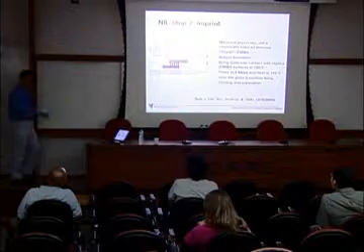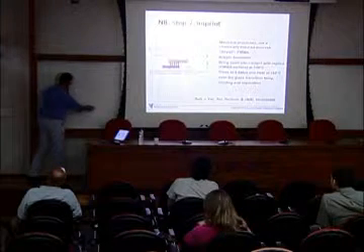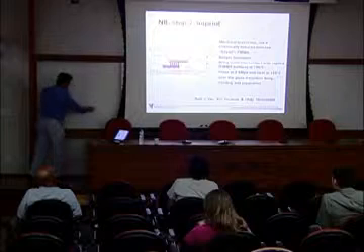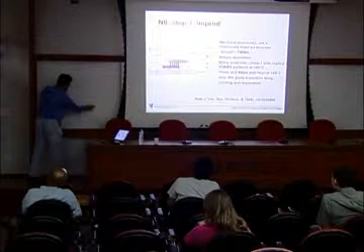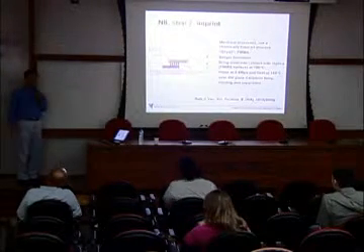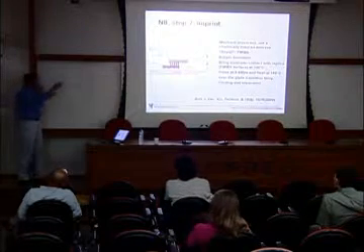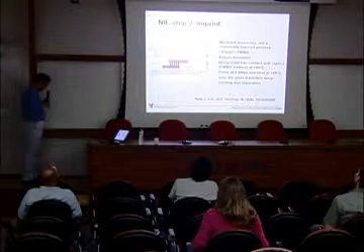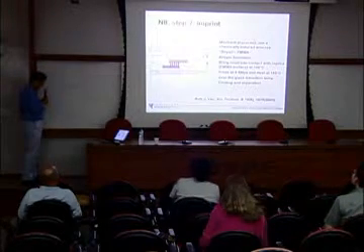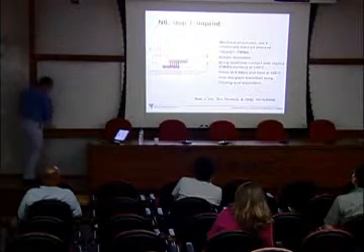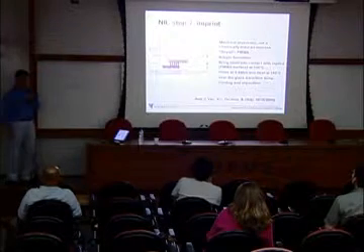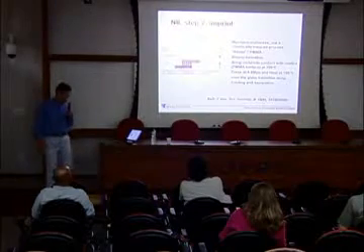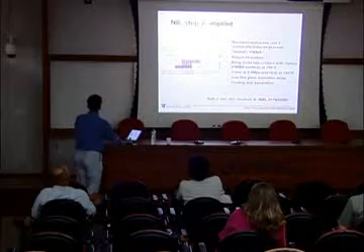In comparison with that, this structure is very narrow, so the polymer material underneath will be transported very well. So this kind of nanoimprint lithography has some limitations in terms of the shapes and features. Those should be investigated further to have a high yield process.